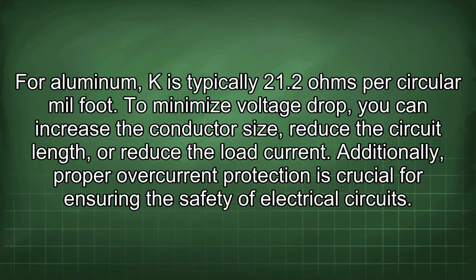To minimize voltage drop, you can increase the conductor size, reduce the circuit length, or reduce the load current. Additionally, proper overcurrent protection is crucial for ensuring the safety of electrical circuits.